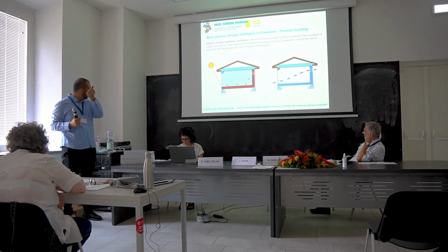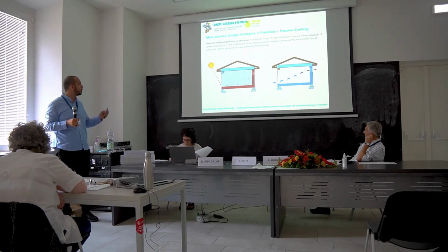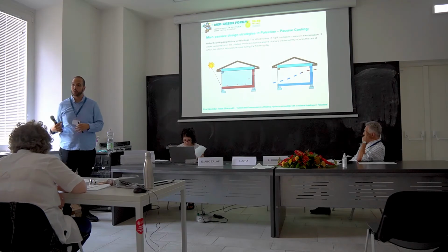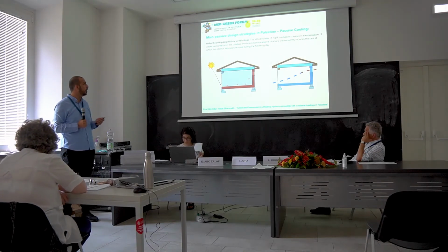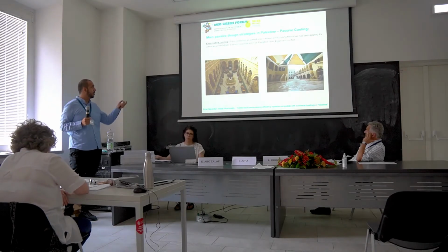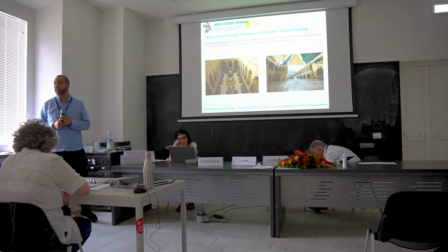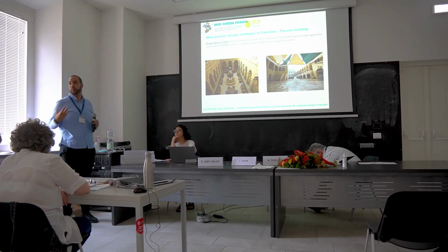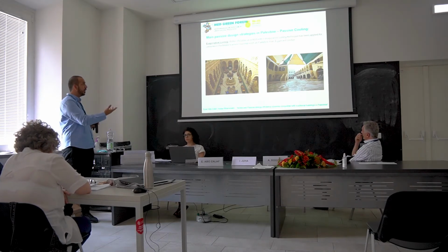We have the radiant cooling or night ventilation. They used it a lot in the heritage buildings, which is to let the thermal mass take the heat into the objects, and at night they open the windows and the doors to do the night flush. I don't have enough time. Lastly, we will talk about evaporative cooling, which they used mainly in public buildings. When they have a court or gallery, they used to put a water element there to act as a heat sink.